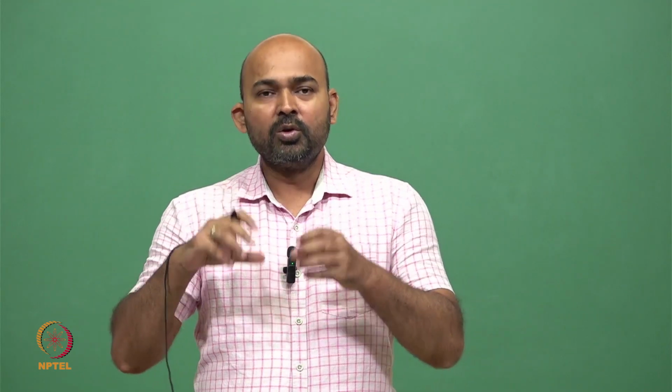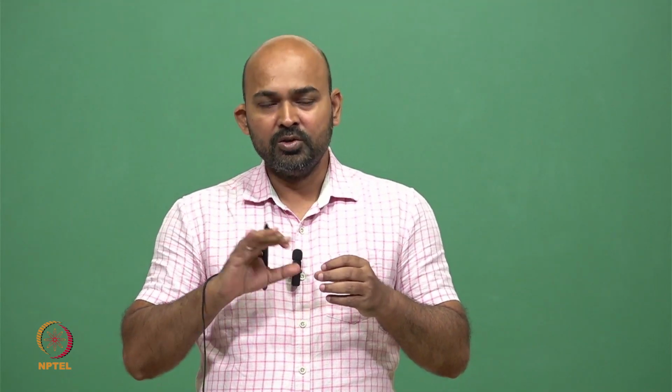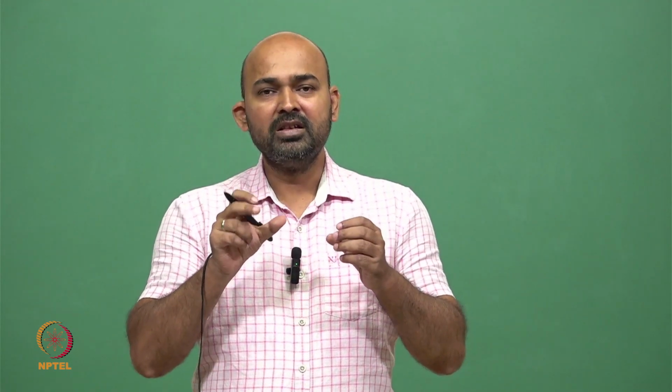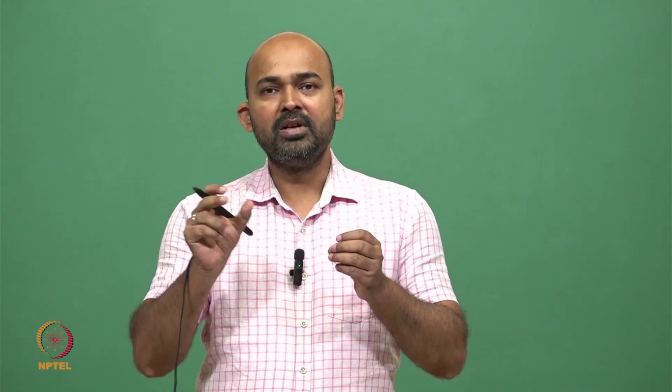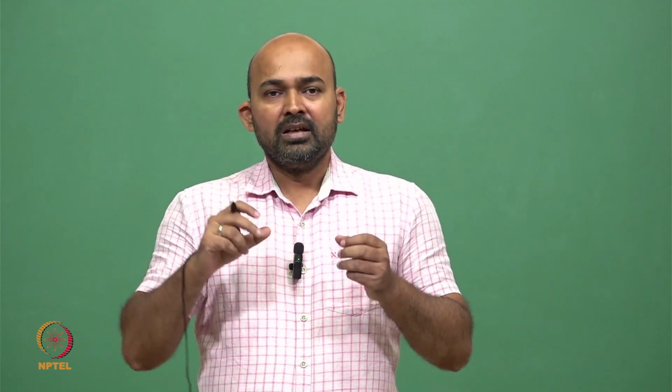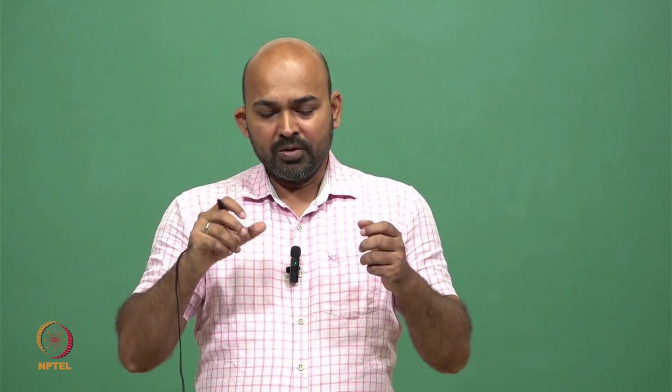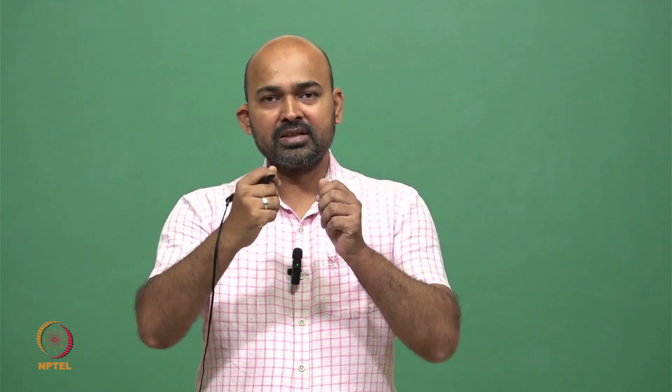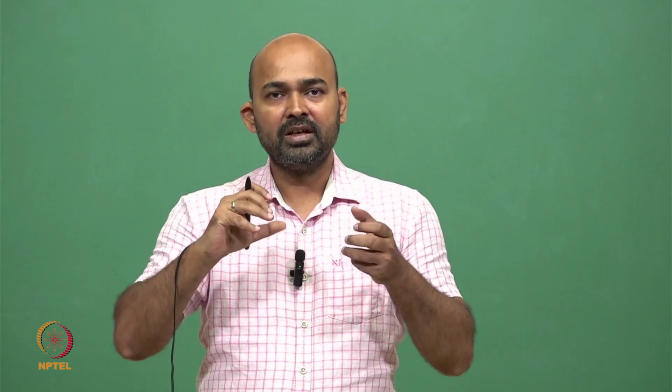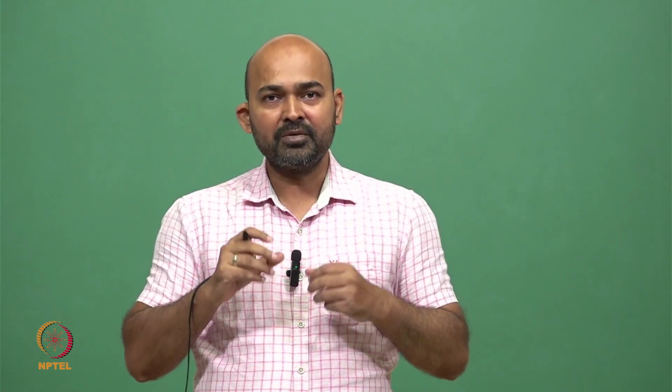Let's say we have pasted a delay line sensor on this shaft. In case of no torque applied in the normal neutral condition, this delay line sensor has a time delay of t. When we apply the torque now, because of the deformation, let's say there is a compression in the SAW sensor because SAW sensor is pasted on this shaft.